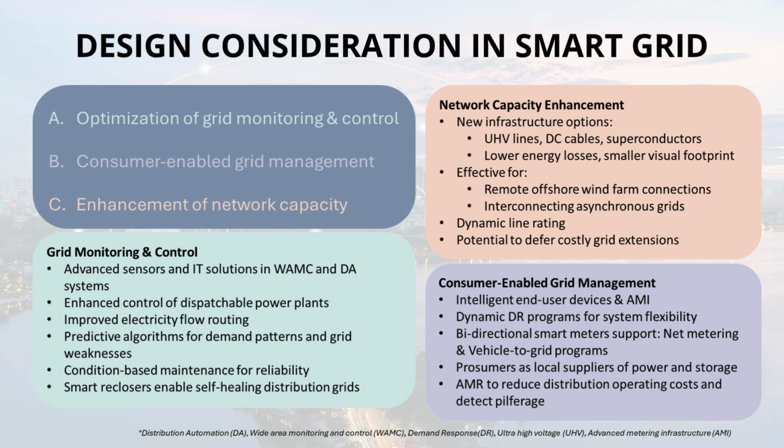Using predictive algorithms based on data analytics and AI to forecast demand or anticipate equipment failures before they happen. Moving to condition-based maintenance, fixing things when data says they need it, not just on a schedule. And a key part of DA: smart reclosers that enable that self-healing function on distribution lines, automatically isolating faults and restoring power to unaffected areas. Okay, that covers monitoring and control.